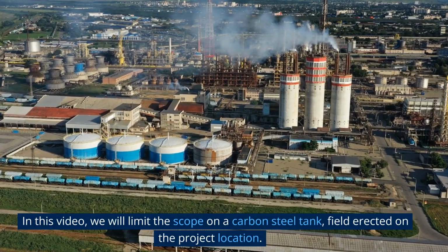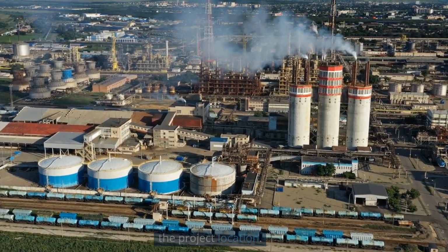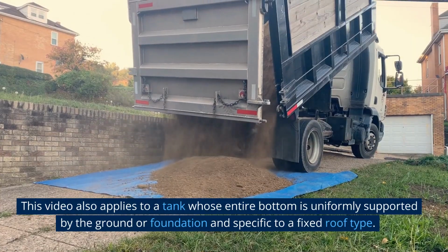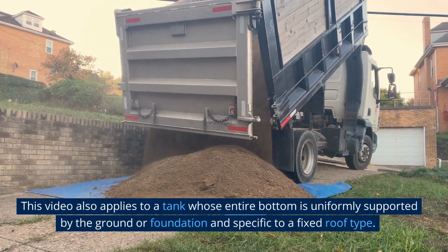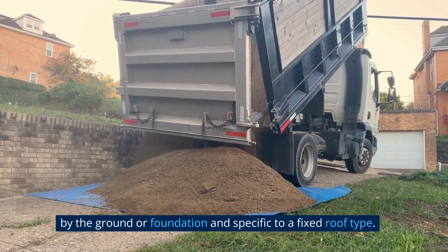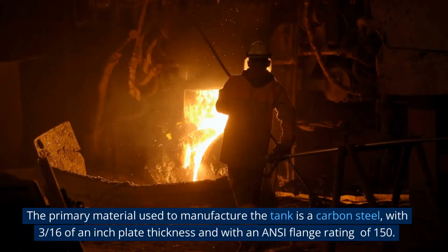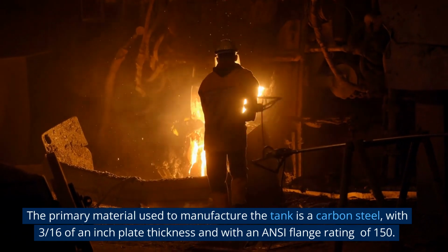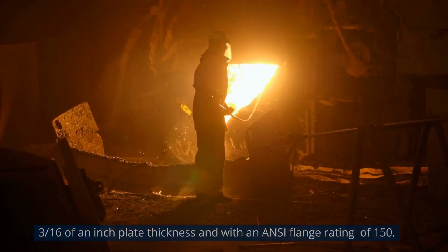In this video, we will limit the scope to a carbon steel tank, field erected on the project location. This video also applies to a tank whose entire bottom is uniformly supported by the ground or foundation and specific to a fixed roof type. The primary material used to manufacture the tank is carbon steel, with 3/16 of an inch plate thickness and with an ANSI flange rating of 150.